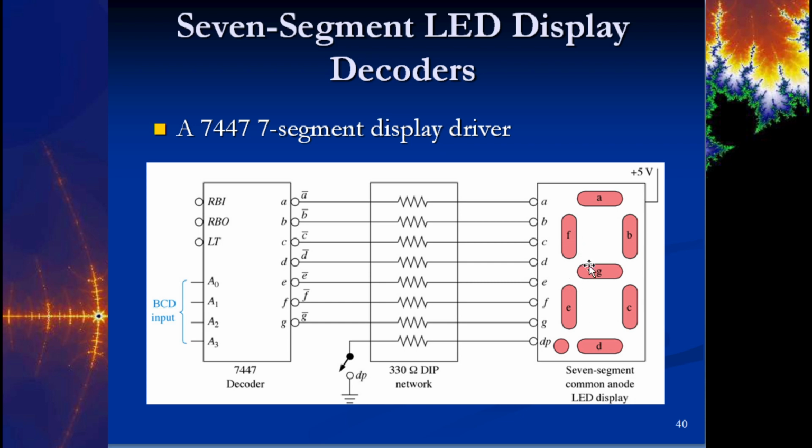LEDs operate between 10 and 20 milliamps, which means if this is a 5 volt out here, which all digital voltage is 5 volts if it's high, then you have essentially an LED to drive over here with this resistor. And so this, 300 to 330, right in that range gives you about 15 milliamps, right in the middle. So if you just stick with this value, then you should be okay to drive these, and you won't put too much or too little current. Too little current, and it won't even turn on, but too much current, and you'll blow the PN junction of the LED.